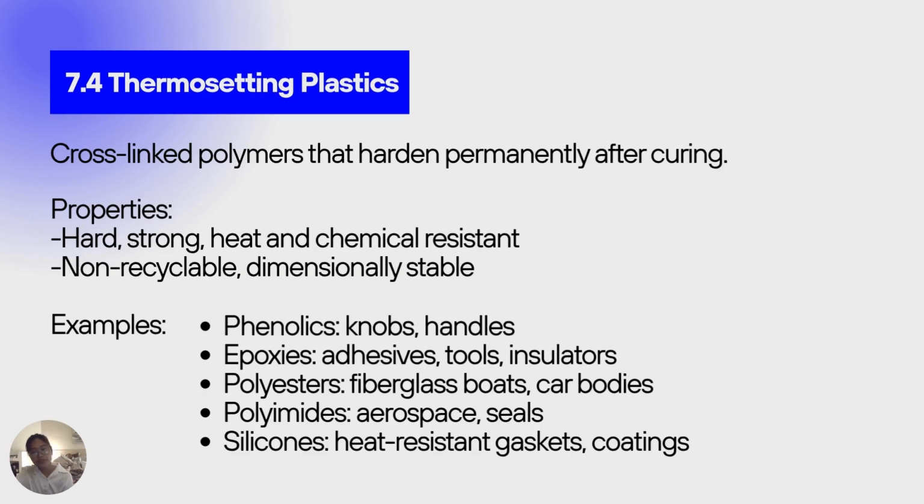The structure of thermosets is characterized by a network of covalent crosslinks connecting the polymer chains. This cross-linking restricts molecular motion, resulting in a hard, brittle, and strong solid. Because of this structure, thermosets have high rigidity and hardness, excellent dimensional stability even at elevated temperatures, outstanding resistance to deformation, creep, and solvents, and also poor ductility. They can fracture under impact or bending.